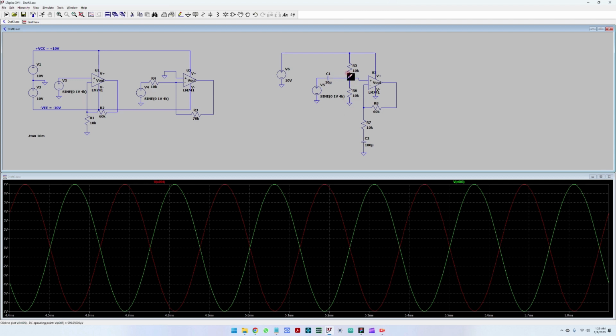Okay, so we are taking the signal going through the capacitor to the DC value here, which is half of the supply. We're having the feedback network here. So the feedback network, as we've discussed, has an amplification of 1 plus the division of these two components. And we have a C2 capacitor here, which is mandatory because we're using ground as a reference, and we need a voltage reference here for the operational amplifier in order to create the amplification.